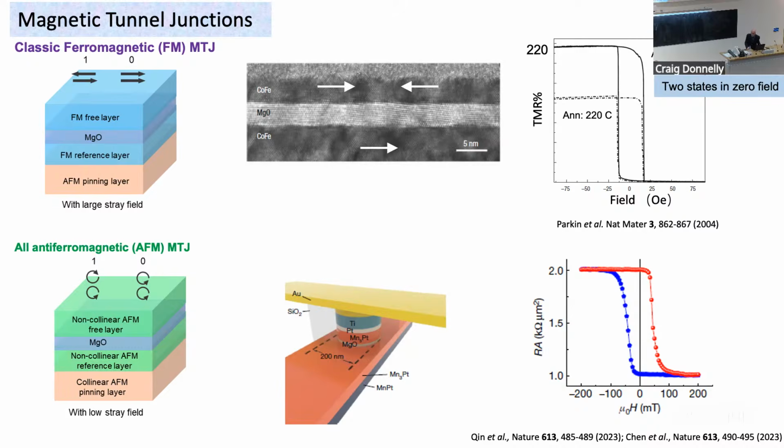And in some structures, the tunneling current can be spin polarized up to more than 90%. This leads to very large changes in tunneling conductance because the magnetic layers will only allow one type of spin polarized electron to pass. And today at room temperature, you see changes in tunneling conductance of several 100%, which makes them, as I said, very exciting and useful for some applications.